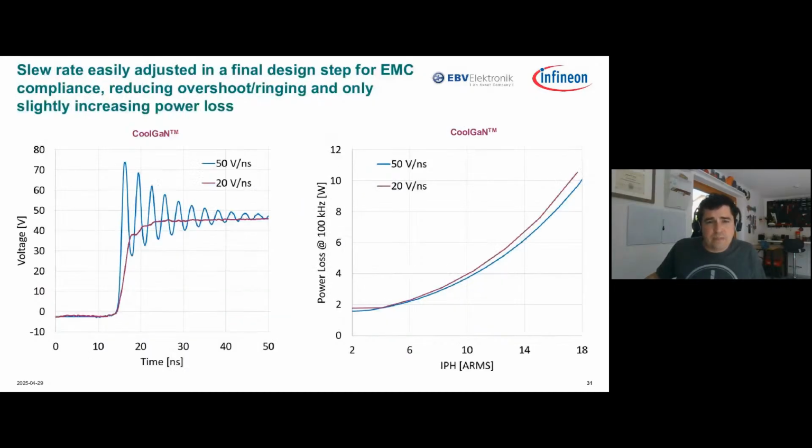However, it is worth noting that you usually don't want your waveform to look like this blue one here. And those efficiency curves I showed you in the previous waveform, all of them looked a bit like this blue waveform here, the silicon and the GaN. We were letting the drain voltage ring because then we get the highest efficiency. Now with a silicon or silicon carbide MOSFET, this ringing would have a lot to do with QRR, meaning that it's very difficult to make it go away.